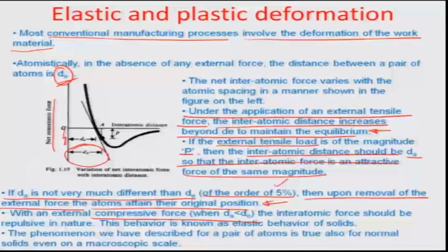So, this 5% d increase in the distance is something which you can probably recall as the elastic region of the material. But beyond this d, if the atoms displace more than the distance 1.05 d, let us say, then you have what you call a plastic range or a plastic flow deformation.